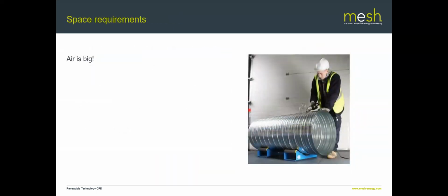Right. So, space requirements. This is the biggest single thing that we battle with as a consultancy when specifying MVHR systems. Air is big, as in one word. So we need to allow space to move air around and for the MVHR plant.